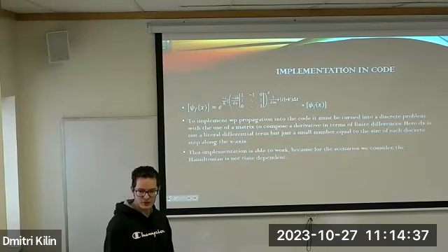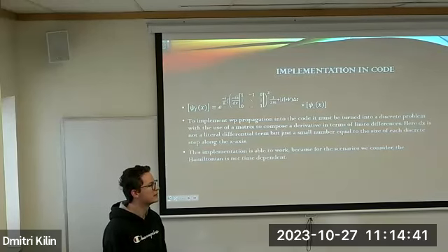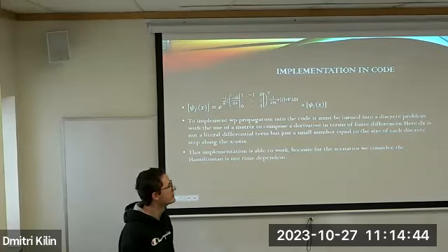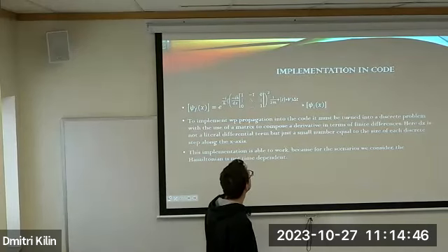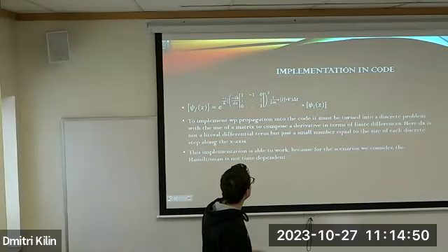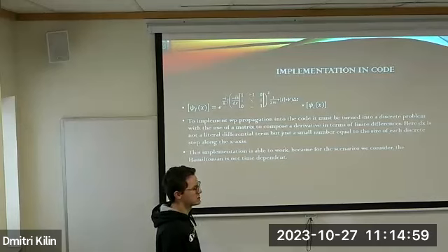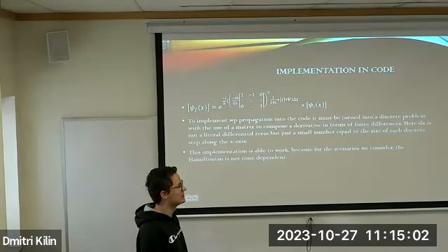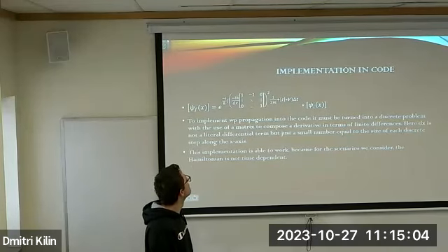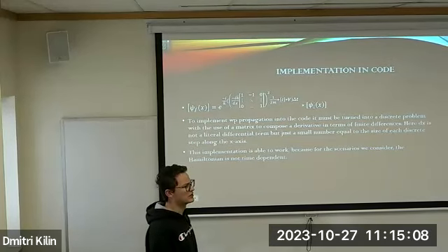So, any more questions? So here you have dx and you also have dt, right? Just delta t. We don't have to have the same time difference every single time, although it may be useful to consider how the system changes in smaller time steps, but it doesn't have to be that way. So I put delta t there just because it can be any time difference that you really want. Within reason, of course. Too far of a time difference in the code kind of generates more errors than you'd like.